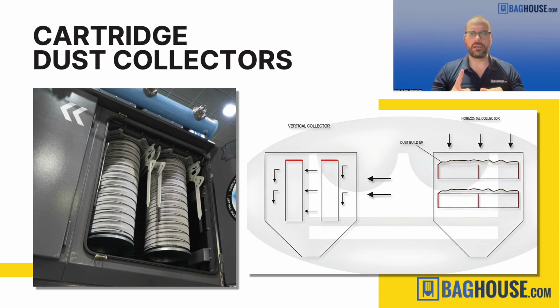If you have any woodworking dust that has anything other than fine, pure sawdust, you want to stay away from cartridges. Why? Because if you have chips, chunks, or strips of anything that come flying in, they will get stuck in the pleats of the filter cartridge. And the pulsing won't remove it, so they can very easily get plugged.